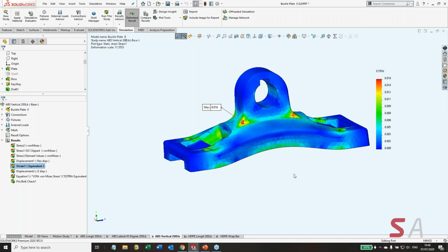Or the displacements. And then the other results, because we have a linear assumption of stress versus strain, it comes up with what the stress is, which is why you can have a stress that is 5 times yield, and all it's doing is saying, look, it's a linear static study. I've got a linear stress strain curve. I'm just telling you what the stress is based upon the strains I've got, which are based upon the deformations. Your material may or may not support it. More on that topic later when we close out this presentation.